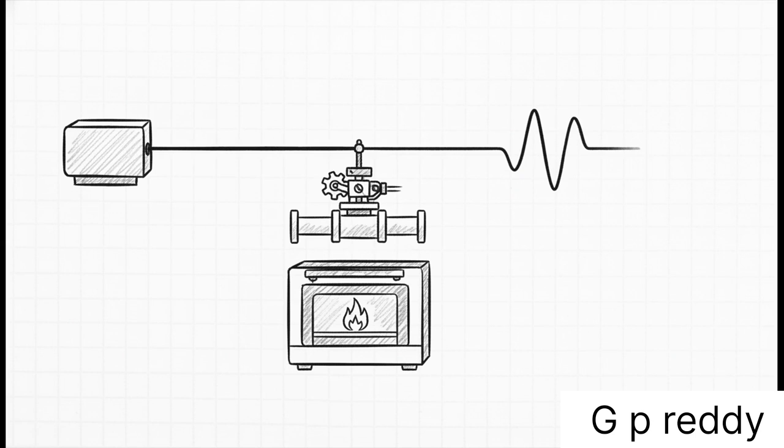This is just the reverse. It's the continuous signal being sent from the controller out to a physical device. Let's say our controller decides that the oven we just talked about is getting a little too hot. Well, it doesn't just want to slam the gas line shut entirely, right? Instead, it sends out a varying analog output signal to a control valve, smoothly twisting it partially closed just to reduce the flame a bit.